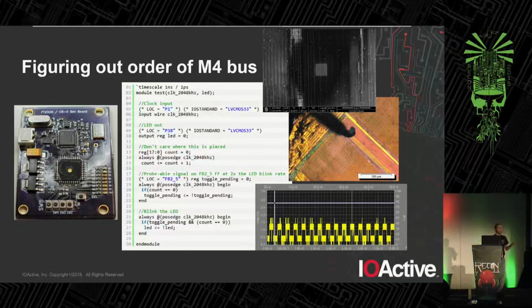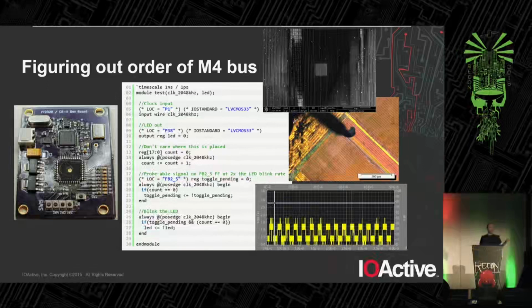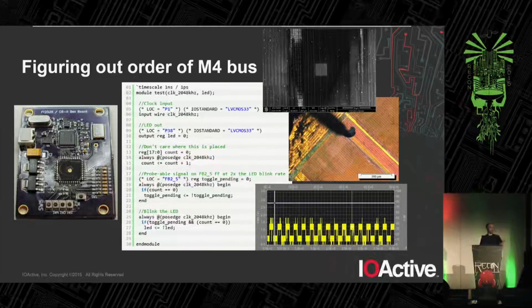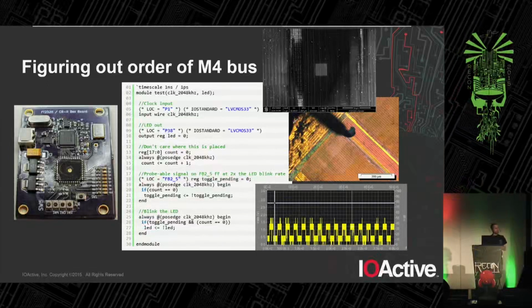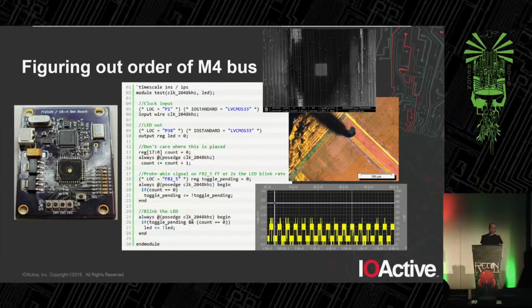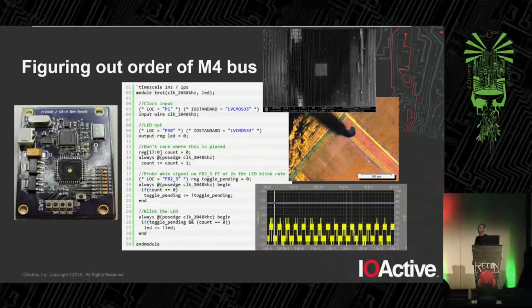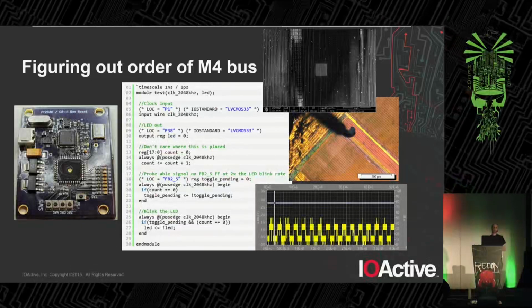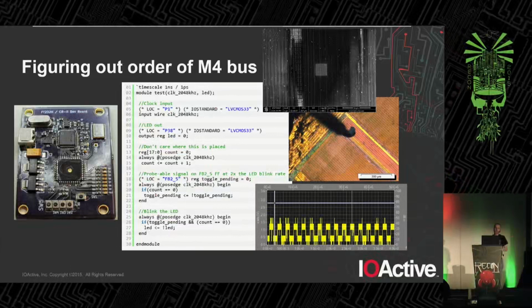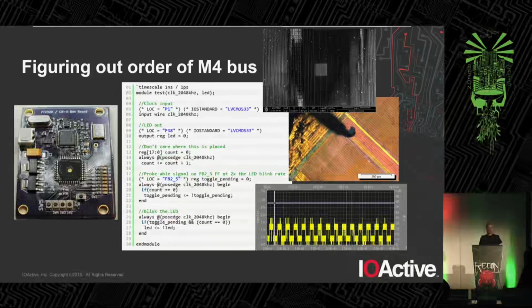Okay, the inputs to function block 2 are probably contiguous. So there's not really that many orderings for the global input pin and these 4 sets of inputs. So let's just try tinkering and see which one works. So I went up to campus, hopped on the focused ion beam, drilled a few holes in the insulator over some wires, and laid down some nice, gigantic 20 micron square probe pads. And then I just started driving signals onto each net.